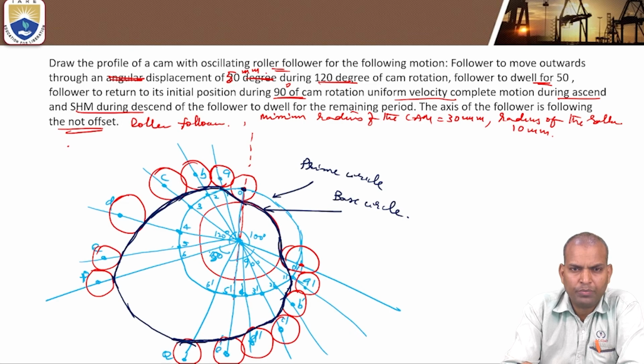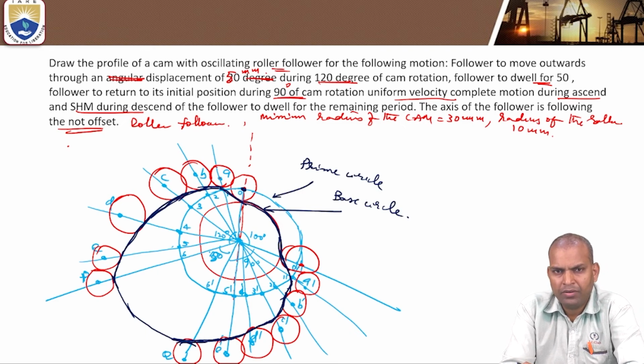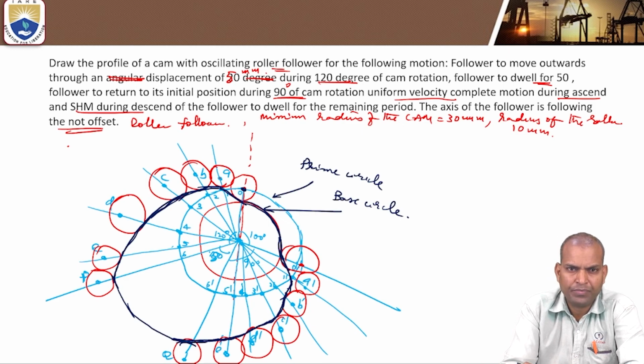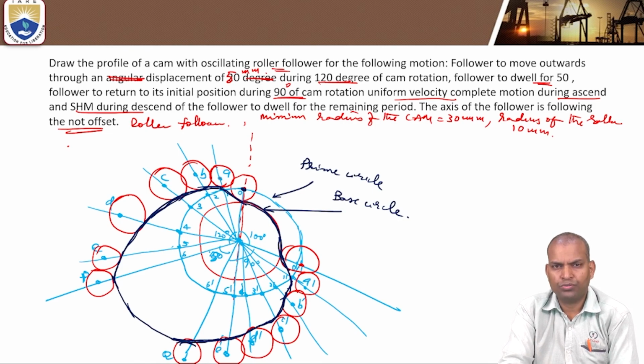So here, what is the exact meaning of the follower? Here the roller followers are nothing but valves in the case of internal combustion engines. Each cam is in touch with only one valve. So the purpose of this cam is valve closing and opening. It controls the valve positions. For operating the valves, these cam profiles are used.